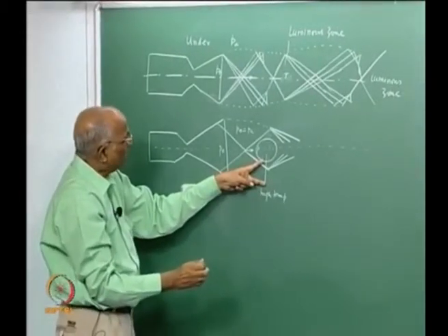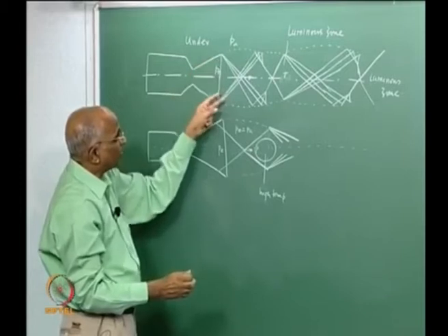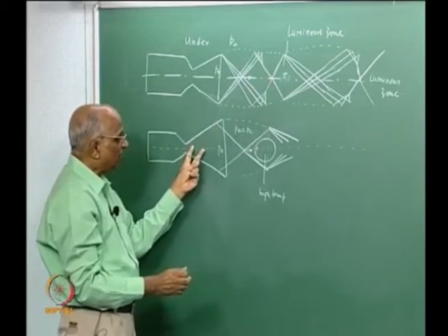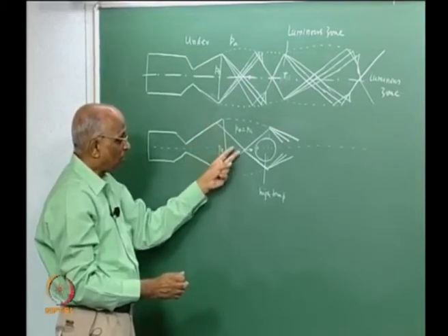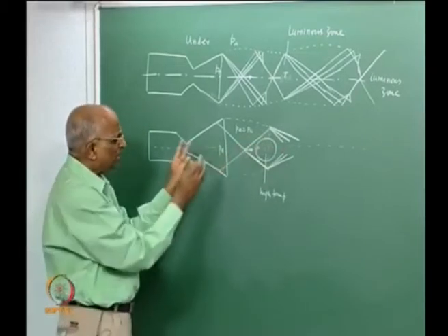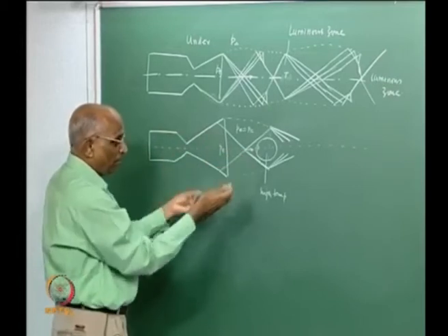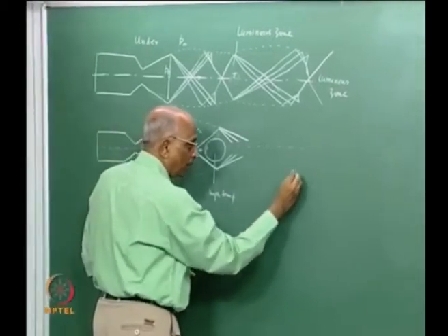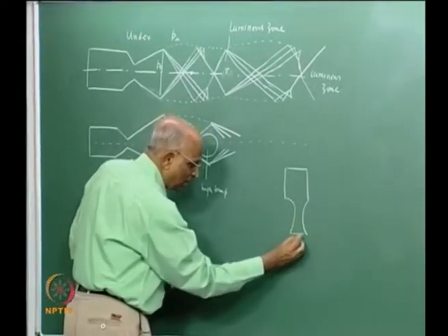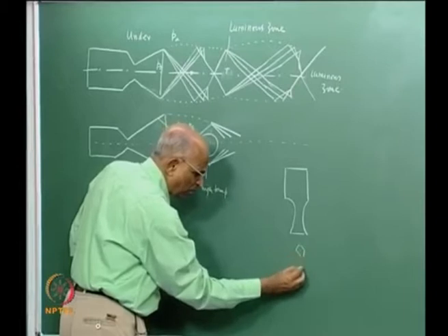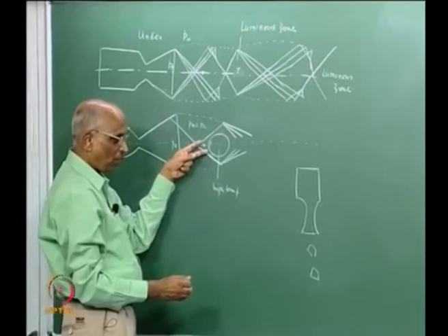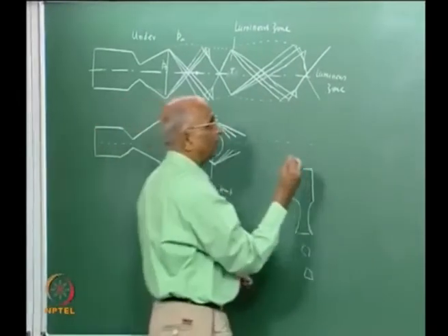Therefore, what is happening in an under expanded nozzle, I have a set of initial rarefaction fans followed by an oblique shock wave. In the case of an over expanded nozzle, I have oblique shock waves which thereafter result in the expansion fan. Therefore, there is a distinct change in the plume if I consider a rocket moving up. If the expansion is not there, maybe I should get some bright spots, and these bright spots are due to the shock wave, and these are known as shock diamonds.